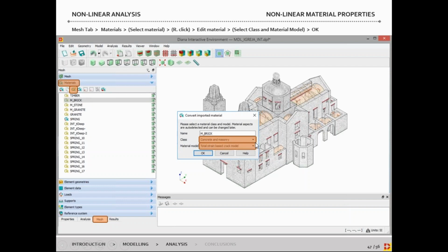Here you can define different material models depending on the type of analysis you are going to run or the considerations that you have for your materials. Also, it is advisable that if we have shell elements, or elements that by default have 1 integration point along the thickness, we should come here and, for the nonlinear analysis, increase the number of integration points. If you work with the previous version, it was this command, or if you work with the new versions, it is this command.